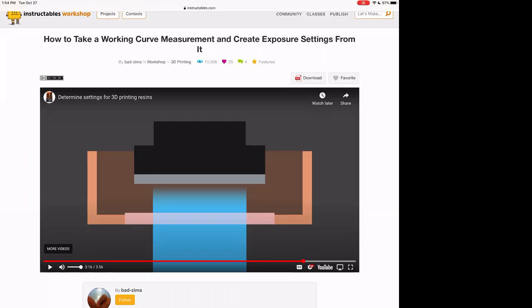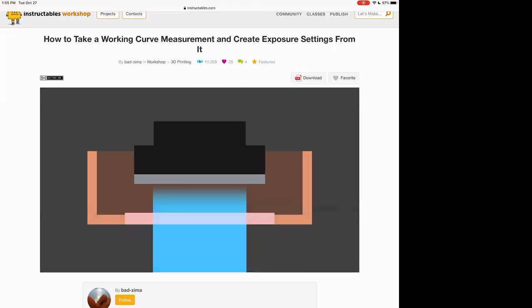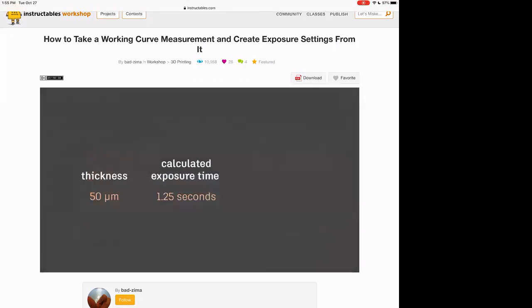Of course, if there's a dead zone, there's a gradient at the window side too, which is another thing that we've discussed. But even though this looks like a big gap here, these resins absorb very strongly. So within 100 microns, the light intensity is dropping off. So it's something to keep in mind. So the layer begins to form where the light intensity is highest, at the surface of the window. And over time, it grows towards the previous layer.